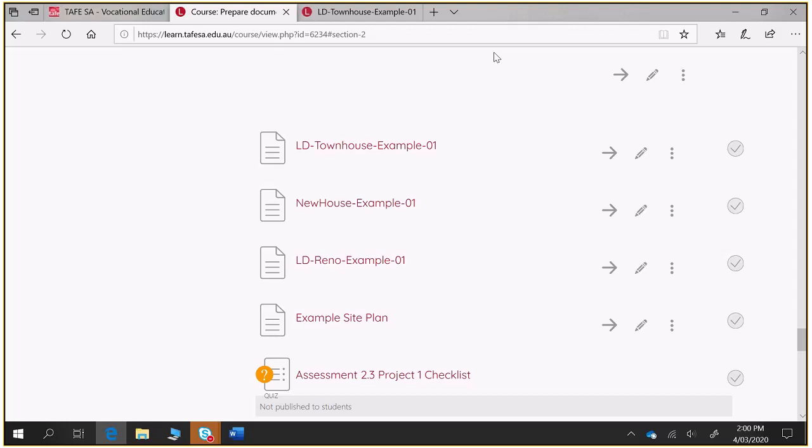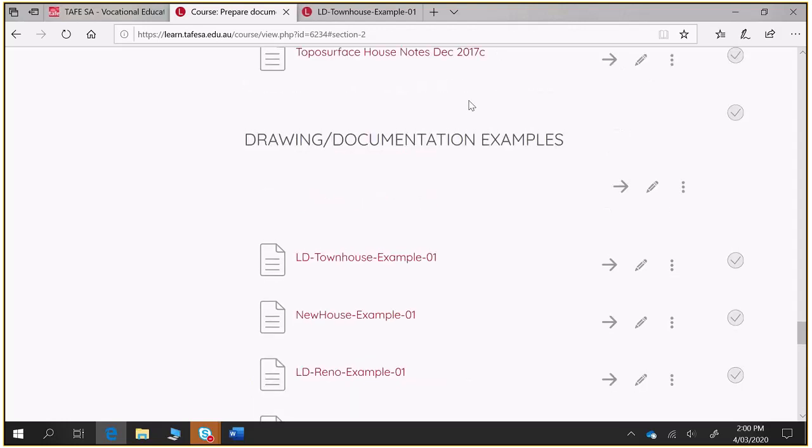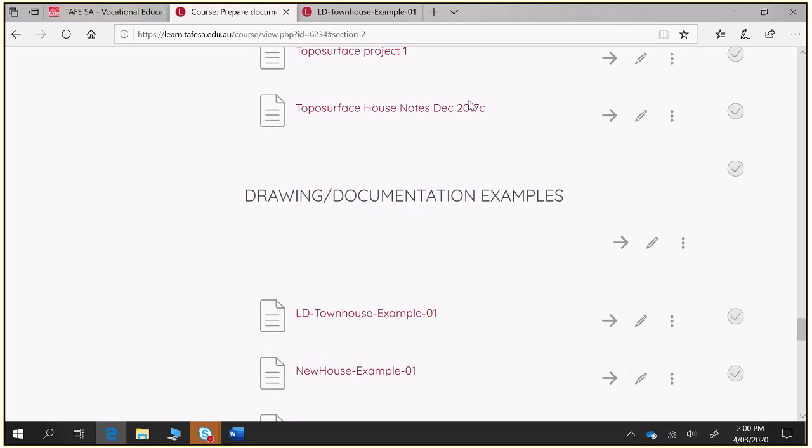Yeah, you can definitely do that, and that's what you do in your bushfire notes. In your bushfire notes, you'd say timber to be selected from this table, but then on your plan or your elevation, you might actually specify something else. And the reason you would specify something else is because if you just say hardwood timber to meet table F of AS3959, your builder might go, oh yeah, sweet, I can use my bow, that's $6 a metre, great. And your client who's very environmentally conscious goes, oh no, another section of Malaysia got chopped down for my deck, I'm not happy about that.